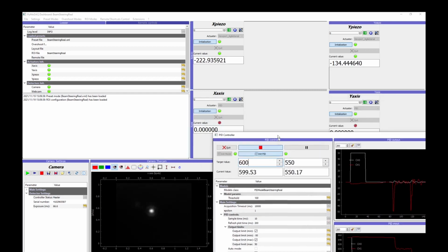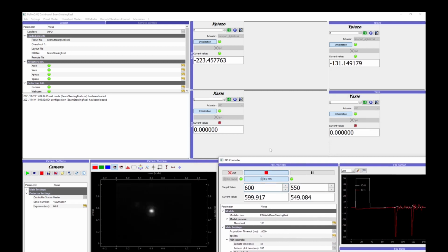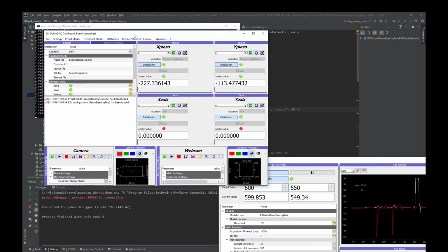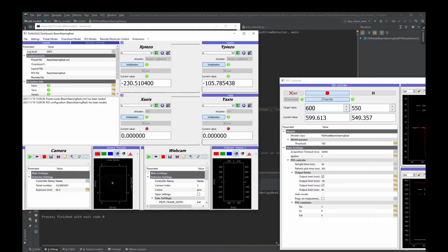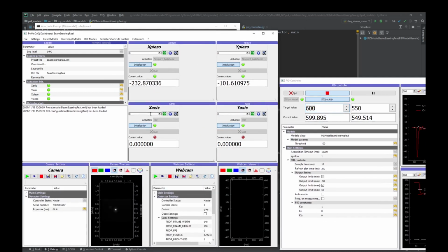But now I don't have to enter the values here because I have two actuators that could do it. So if I'm now entering some positions, I'm going to move that around so you see what's happening. All right. For X, if I tell it to go to 400, it's setting the set point to 400, and the system is moving because the PID loop is running. Same for Y. If I want to go to 700, let's say, it's getting there.